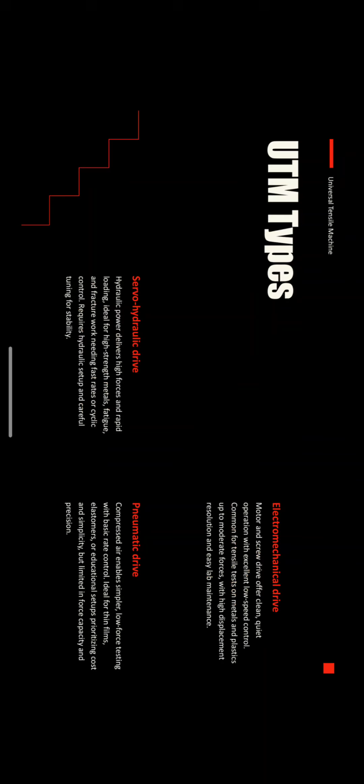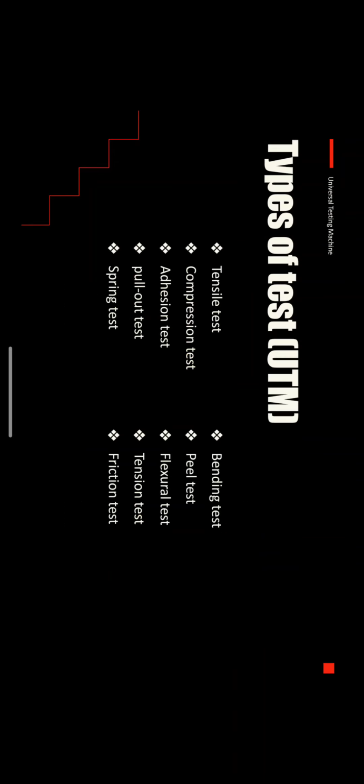Pneumatic drive: compressed air enables simpler low force testing with basic rate control, ideal for thin films, elastomers, or educational setups, prioritizing cost and simplicity but limited in force capacity and precision.